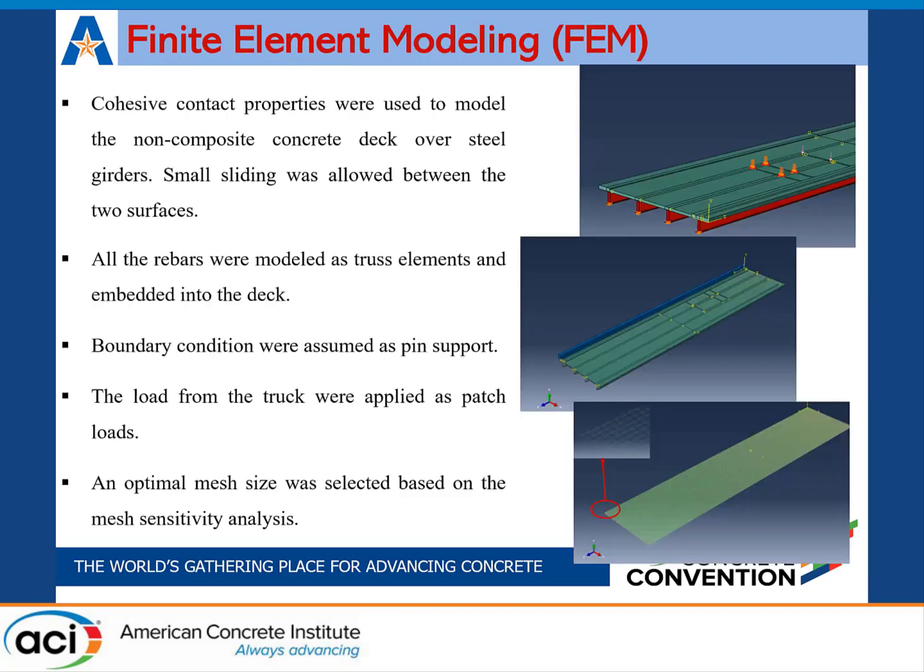Prior to applying a retrofitting strategy to a full-scale bridge, a finite element model can be utilized to evaluate the efficiency of the retrofitting options. Sometimes experimental studies for different retrofitting options can be time-consuming, expensive, and have some constraints. So the FEM model is a suitable option to get around that kind of situation. Through the FEM model and cost analysis, bridge owners can decide which retrofitting is a suitable option for deficient bridges.